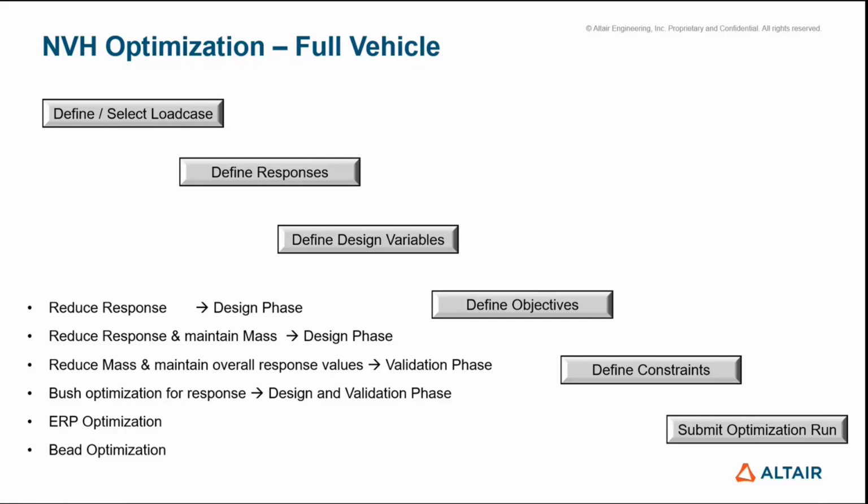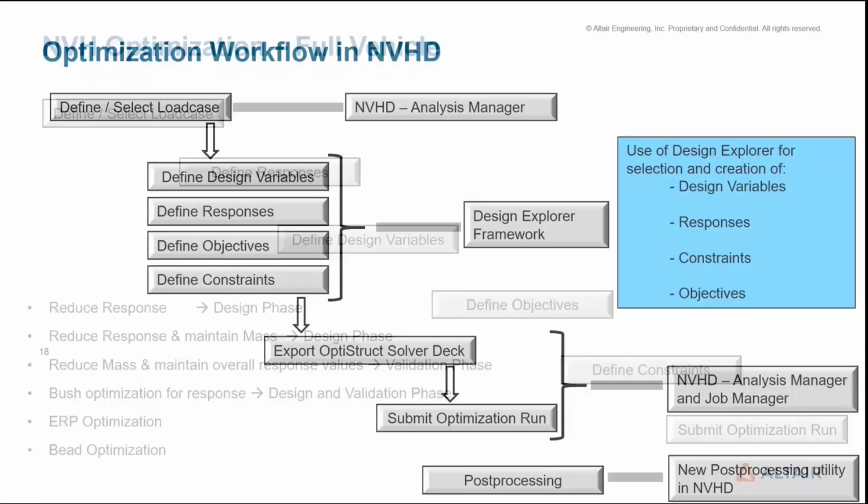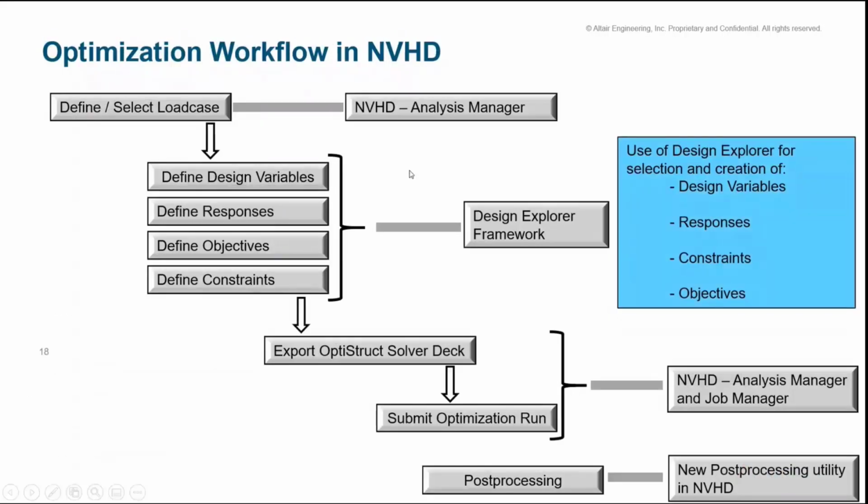So it's very necessary to have a seamless, user-friendly workflow, so that the optimizations can be set up pretty quickly. Inside NVHD, Design Explorer is used for defining the design variables, responses, objectives, and constraints. To start with, defining or selecting a load case happens inside NVHD using Analysis Manager. Then, to define the variables, responses, objectives, and constraints, we have completely used the Design Explorer framework.